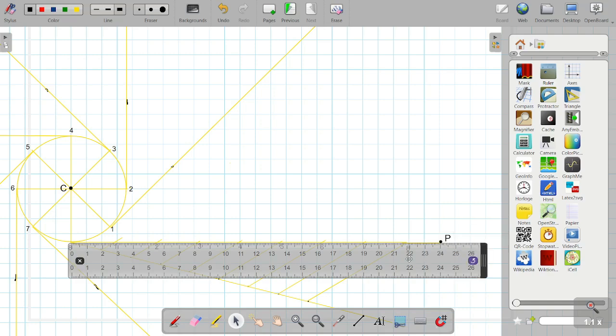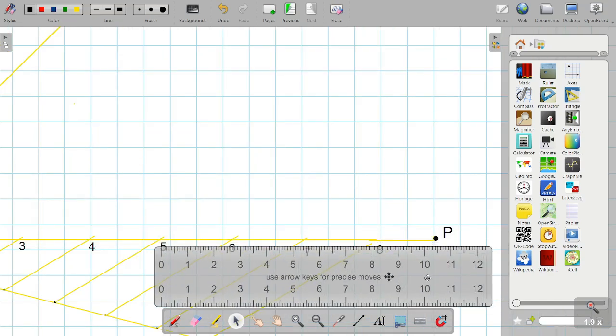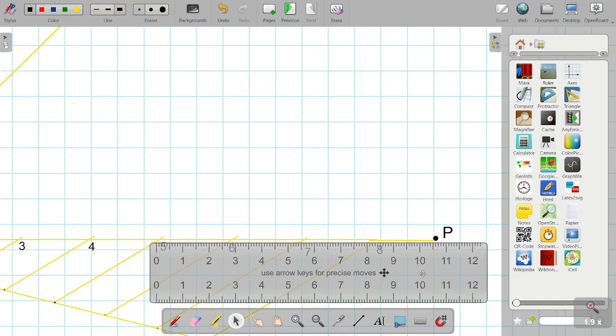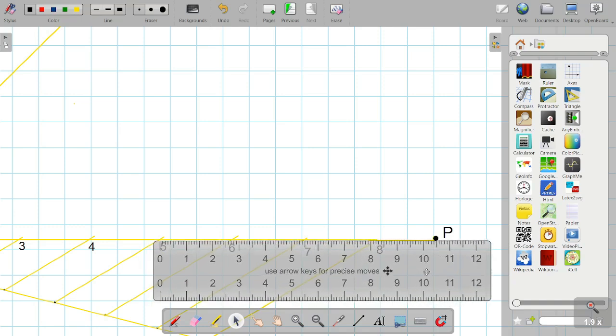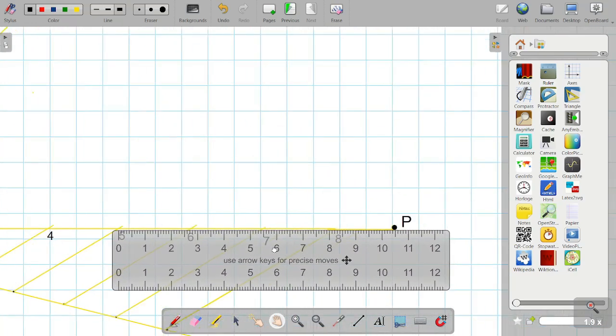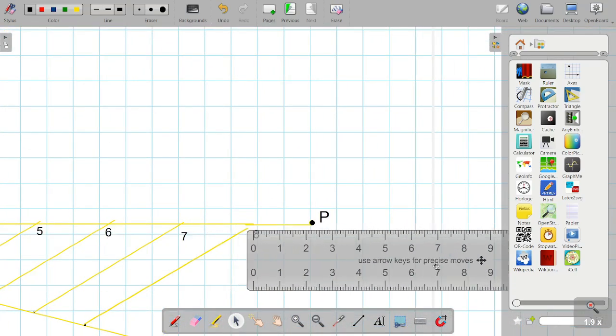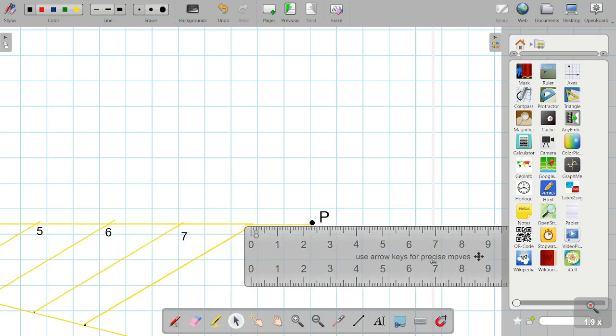So this is point P for us now. Now we will measure the distance between any of the points, let us say 4 to 5 or 5 to 6. So this is coming out to be 2.7. So what I will do is measure 2.7 from point 8, which is coming outside the point P. So no need to measure. If it is coming inside, we have to measure and name that as point 1 dash, or you can also name it as point 9.